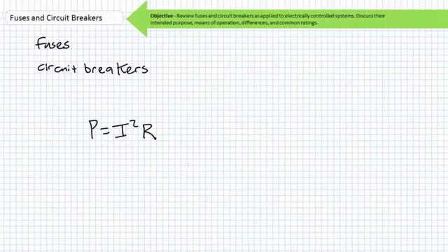It is incumbent upon any individual using any expensive electrical apparatus they wish to keep in working order to continually monitor current. Avoid high current for sustained lengths of time. Pay attention and be prepared to shut it down at any moment you observe unusually high current for a sustained period of time, smell or see smoke, or worse yet, see flames shooting from the system you're working on. Know where the off button is and make sure you've got access to it.